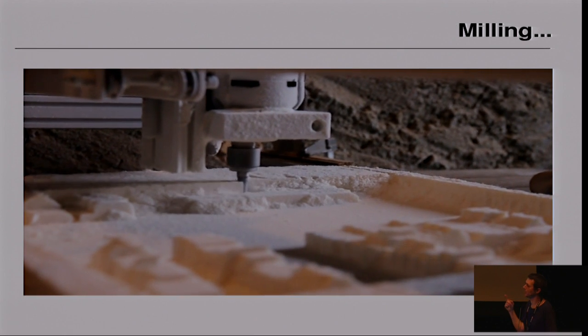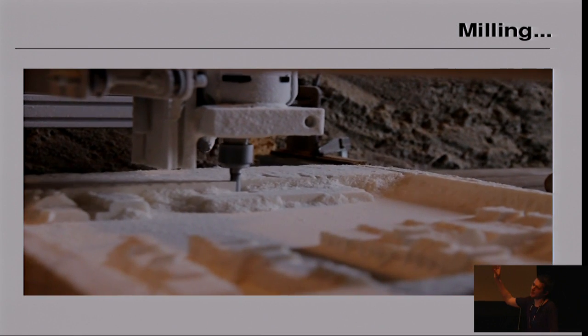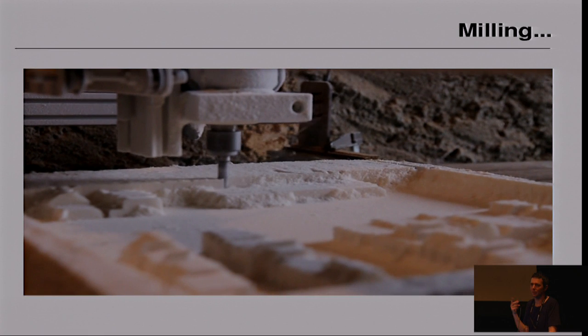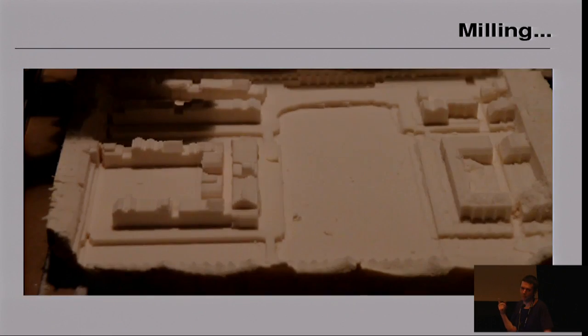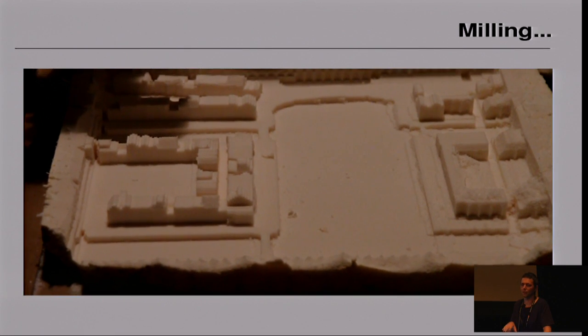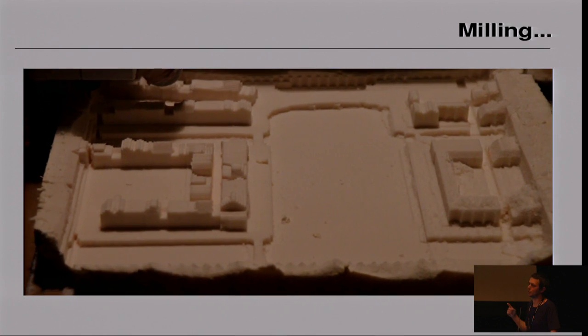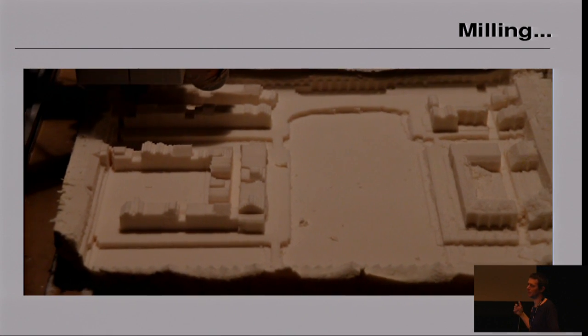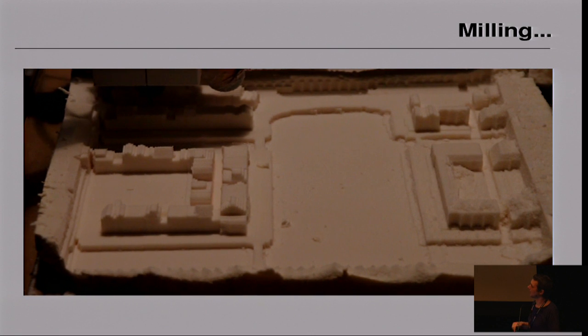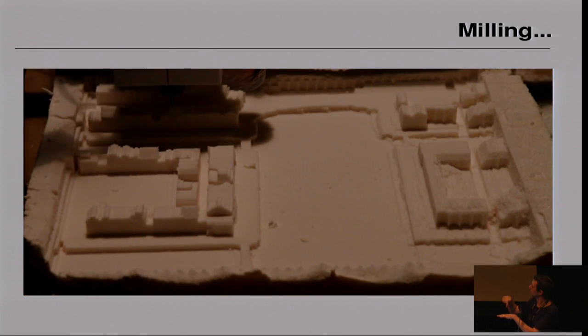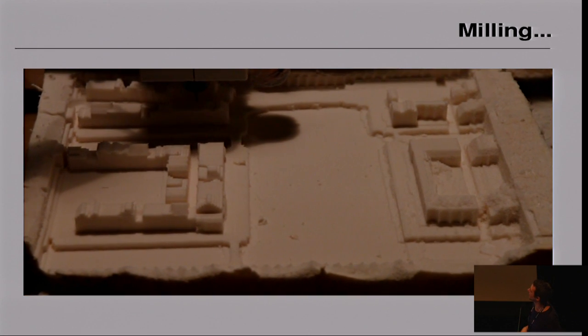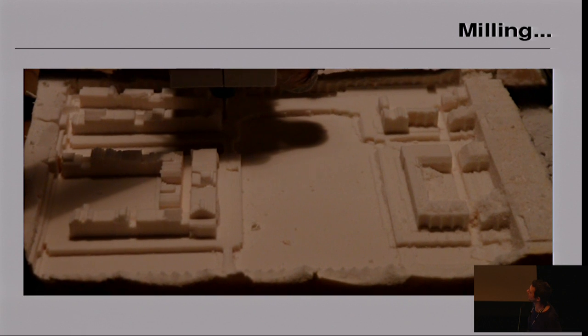So you can define the speed. On my own, I cannot adjust the speed of the spindle by the software, but in the BlenderCAM, you can specify for each tool the rotational speed, the feed rate, the security distance, and this is the finishing path.